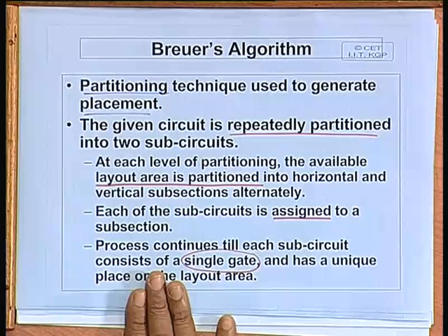This method is good, but in general it will not lead to very good placement, because you are basically cutting it with respect to certain criteria, but the final solution you will be getting in the process may be one where the net length may be pretty long. You are not putting enough emphasis on the interconnection, you are putting more emphasis on the gates or the basic components.